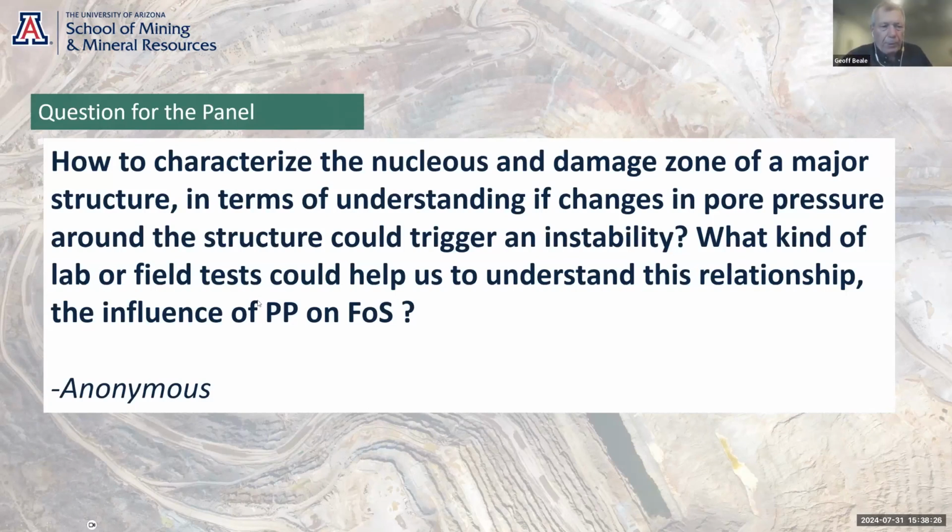So I think the short answer again is piezometers. So look at your piezometers, and let's say you have a structure, let's say 20 meters behind a pit wall, and if you excavate the pit wall and the pore pressure in that piezometer drops, what it's telling you is probably the structure is dilated, and so the pore pressure drops, but it's also telling you that there's no recharge getting into that structure.